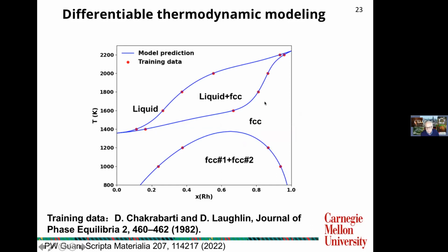Okay, but in the previous, what were the parameters that you're looking at the gradients of? The parameter is the parameter in the Gibbs energy of different phases. So, for example, in the FCC phase, we actually can expand its mixing enthalpy into an RK series. We have a regular parameter, subregular parameter, and we train this parameter in the Gibbs energy. I see. Okay.